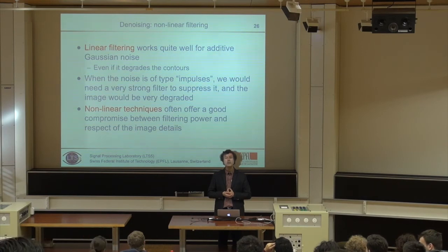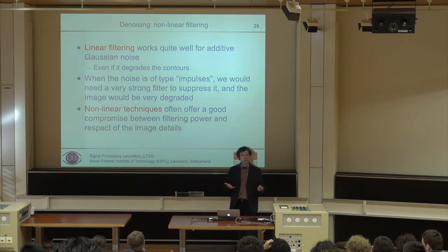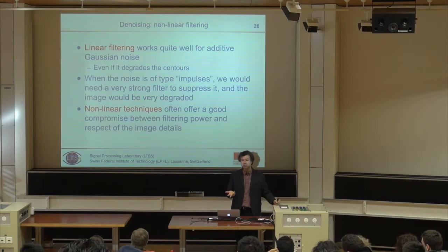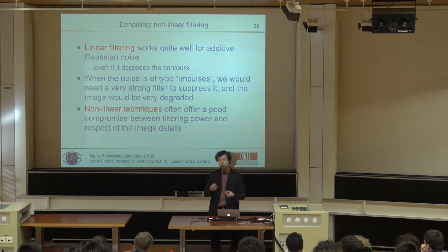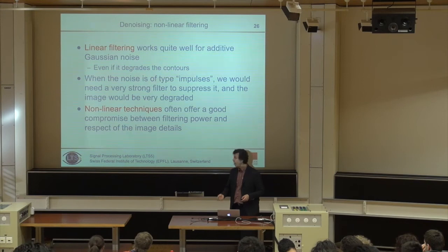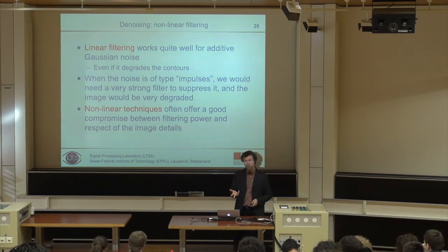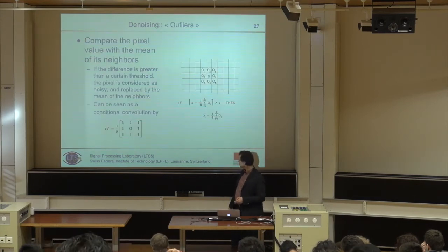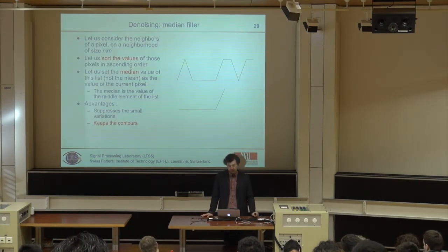Oh, come on, yes, you do a fast Fourier transform. So, doing a linear filtering means doing a convolution, and you can do it extremely quickly by a fast Fourier transform. So that's the advantage. It's very simple. Drawback, well, it's linear, so it doesn't select whether you remove noise or data. In the non-linear versions, you don't have the advantage of very fast implementation, but you can do more sophisticated stuff. I will let you read what I have in those slides. I will just focus here on one of them, which I like very much.